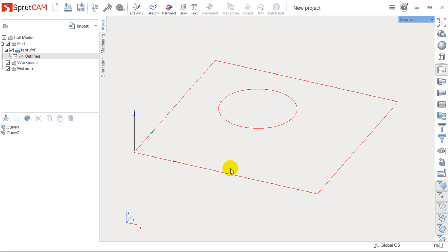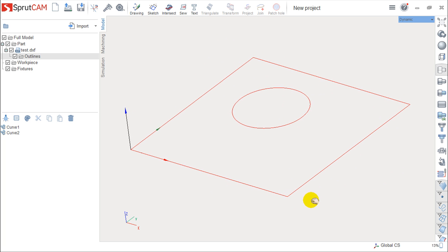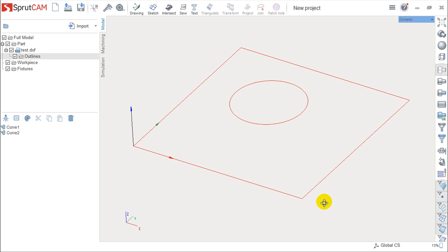Today we are going to talk about 2D contouring, a topic we started in the previous video with the whole machining. To remember one thing we said, which is very important for this lesson: we don't need any solids to create toolpaths. We may only have lines, contours, and arcs, and it is enough to create this type of machining. So I've imported one DXF format file with these contours that you are seeing now, and we will use them to create a couple of examples.